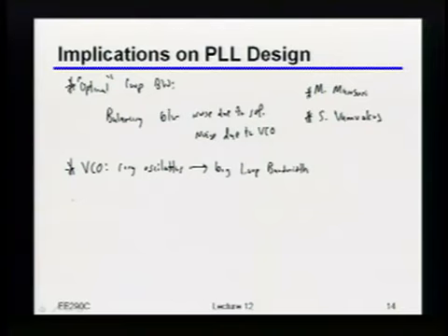Right? Okay, well, now let's say that I had my VCO, instead, actually be an LC oscillator. And not only did I use an LC, but I was really, really careful. I really optimized the hell out of the phase noise of that thing. And I did such a good job that it's better than the crystal reference that somebody gave you. Which, by the way, is not actually impossible, because remember, those crystal references are like 100 megahertz, and these LC oscillators could be at 10 or 20 gig. So that can actually happen.